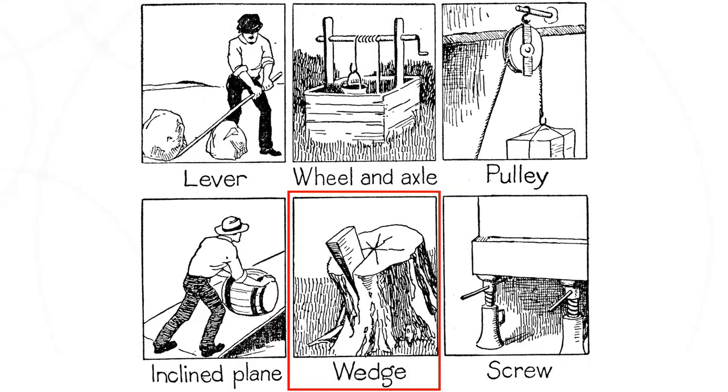And you're going to have some pretty big problems there, which is why that class 2 soil, or the A1 or A3 soil, the class 2 soil is the best because it only requires 85% compaction under the haunches. So you're going to want to use that better material, that more expensive and more reliable material of that A1, A3 AASHTO classification soil, because you don't have to compact it as much, so it's going to be easier and it's not going to cause that wedge.